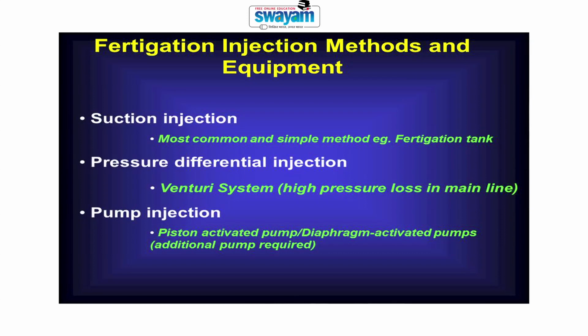Water soluble fertilizer is mixed into the tank, and this fertilizer solution is injected into the water system and applied directly near the crop. Another option is pump injection, in which different types of pumps are used, using the same water pressure or a different electrical pressure, for applying fertilizer solution into the drip irrigation system.